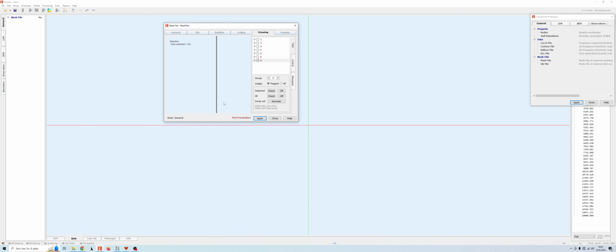So I've made it with a lot of detail at the throat, where the highest detail is needed, and then it's a bit more rough through the waveguide, but it's still a ton of points, which generates a more or less smooth curve. On the back side of the waveguide, I've done a bit more rough steps, but it doesn't really matter because it affects the radiation pattern of the waveguide relatively little. Now, there's just one problem, and that is this part.